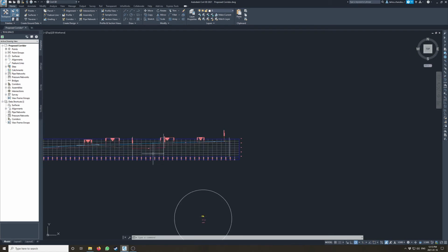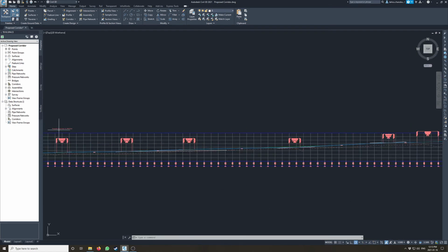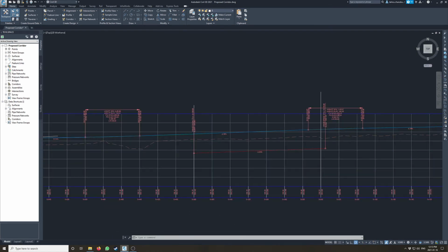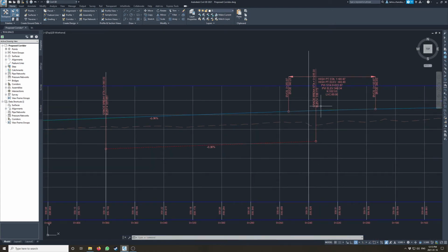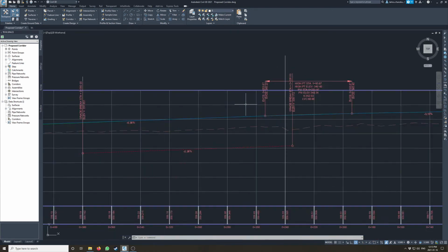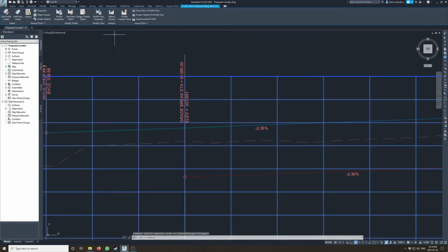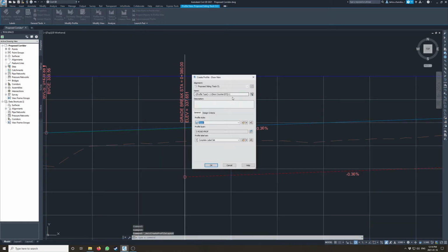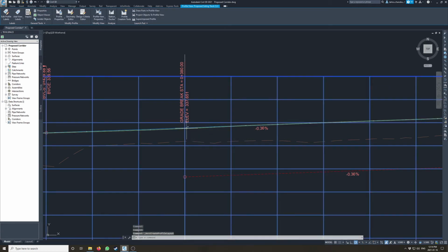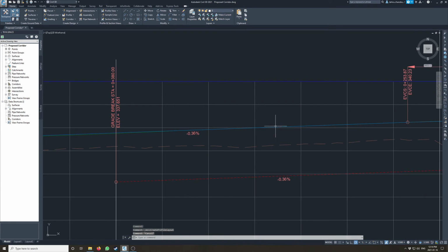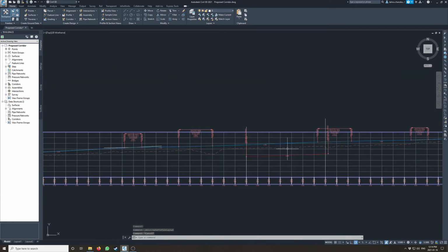So first of all, you can go to your top rail profile. I've already created a ditch here. I've created it from 235 to 380. And the way you do that is you select your profile view, profile creation tools, and you can create a little ditch here. And I've just made it so that it follows my track and it's a certain distance down.